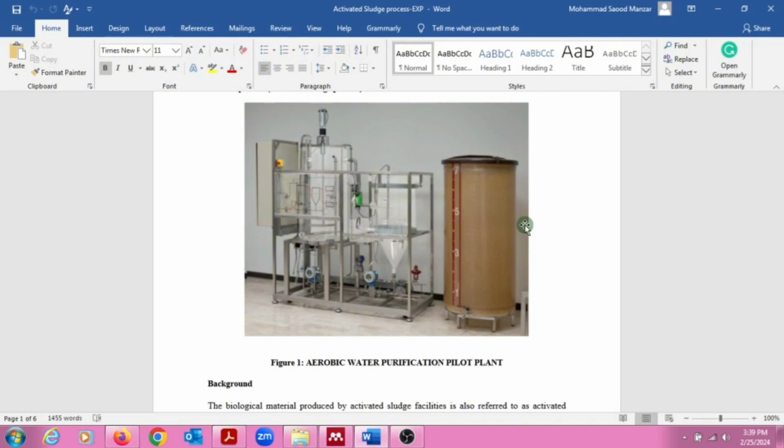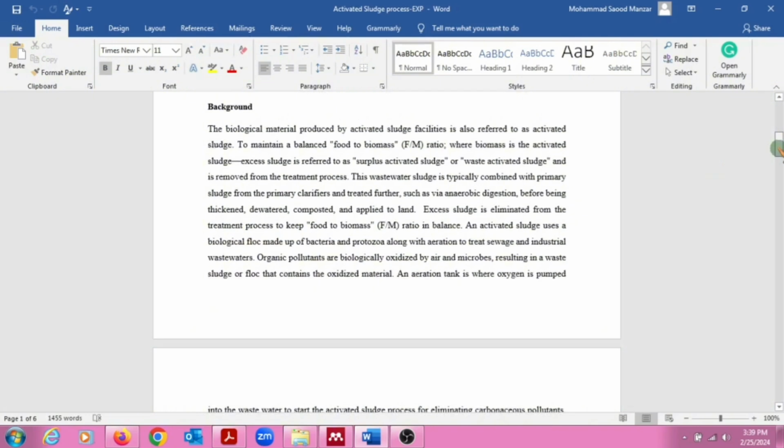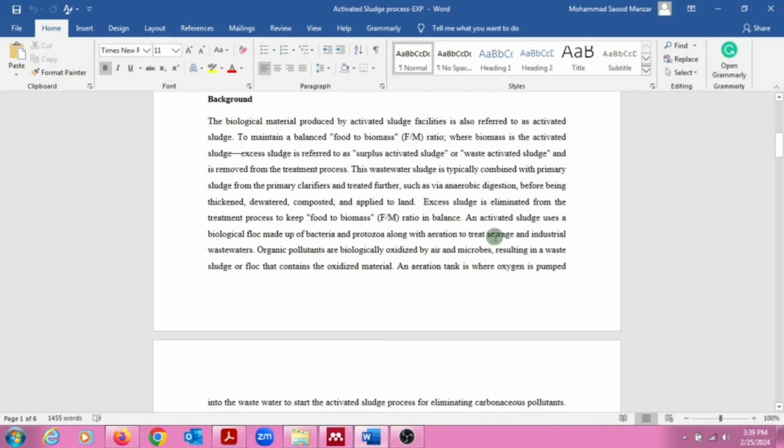Okay, now our main concern is to understand how we carry out the tryouts. There is a lot of theory, and you can read books like Metcalf & Eddy and your manuals. So the fundamental is that the activated sludge system essentially consists of the aeration tank, followed by a particle separator. In the aeration tank we have raw sewage, which mixes with a group of flocculent solids. The solids contain a high amount of bacteria, you can see the theory here, and in the state of liquid sludge a lot of microorganisms, primarily bacteria, live, feed and reproduce themselves to remove the organic substance of the sewage. At the same time, absorption and bioflocculation occur in the mixture, so the colloidal and suspended substances in the sewage are also removed by the action of activated sludge.